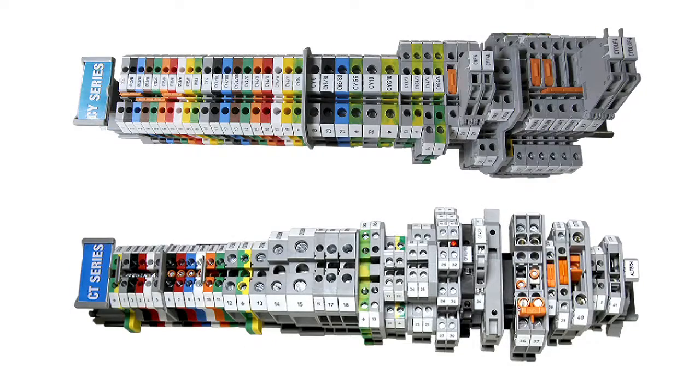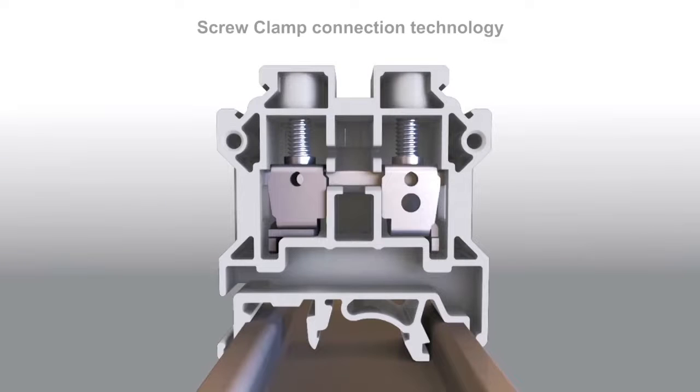Okay, so screw terminals are mainly used in the distribution of electricity in homes, warehouses, plants, factories, and inside all types of panels and junction boxes. They've been around for a long time, and that's really also the connection technology which is most dependent on human interaction, since I do have a screw that needs to be tightened, and that has different torque values, so that really depends on the human to tighten the screw. And when there's usually a human involved, there's also room for more failure.